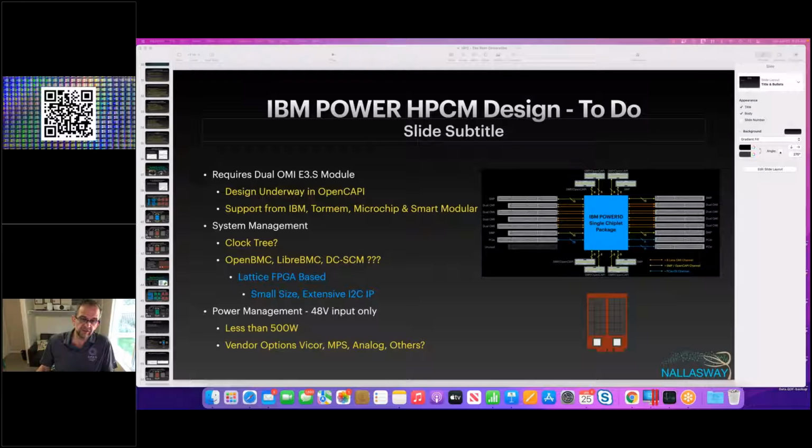We bring the 48 volts in through two large pins, and it's completely cabled because there's no motherboard. It would be cabled to a frame, so you could slide this into the OAI chassis and connect into the rest of the OCP infrastructure through the OAI chassis. That's the idea. That makes sense, but when you cable it into that OAI chassis, what are the signals that are running across there? I mean, that's defined in the standard, I suppose.